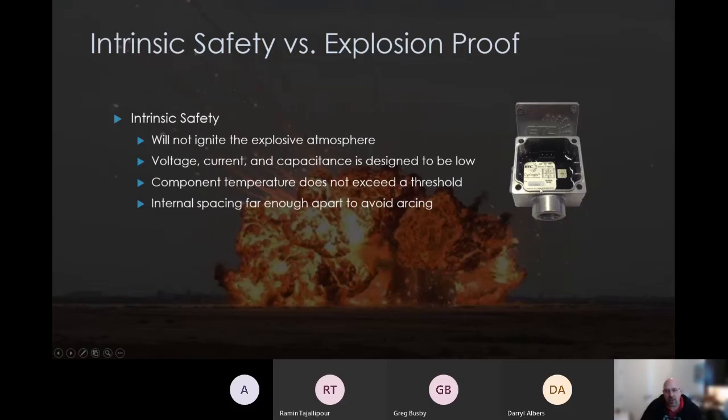And that also, that epoxy will dissipate heat. So that also helps us to spread out the heat generated by a really hot component. So in some cases, especially if you have things like radios in a hazardous location, you'll see that at least part of the board, or the transmitter part, is encapsulated in some kind of barrier with epoxy in it to keep the surface components low and prevent it from arcing.